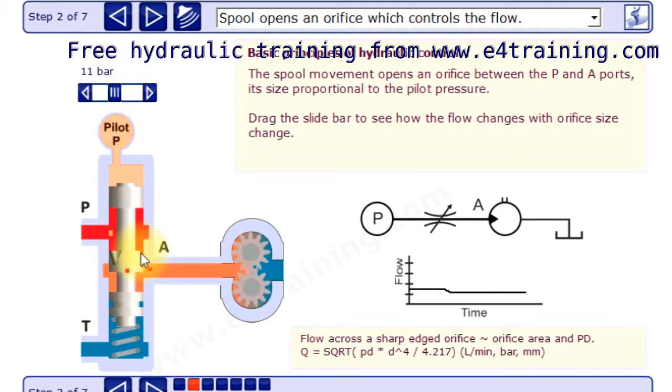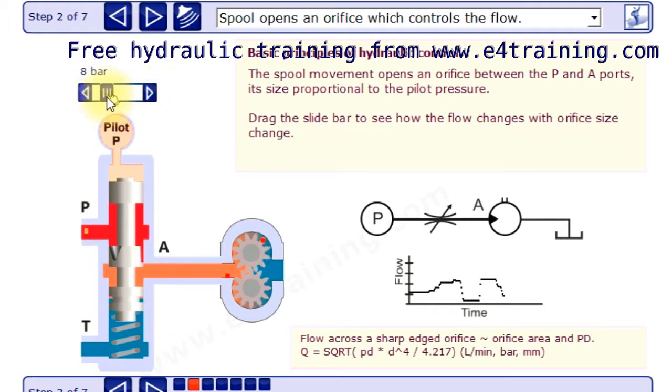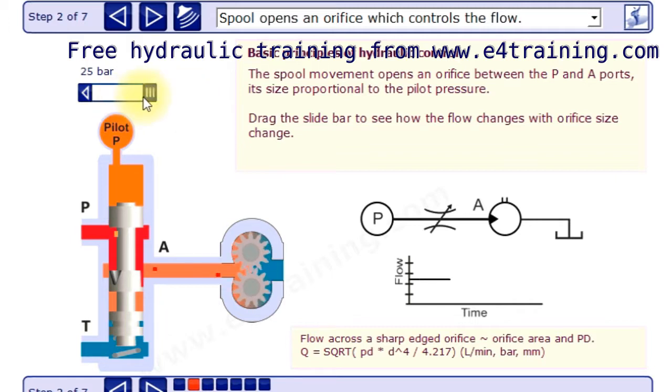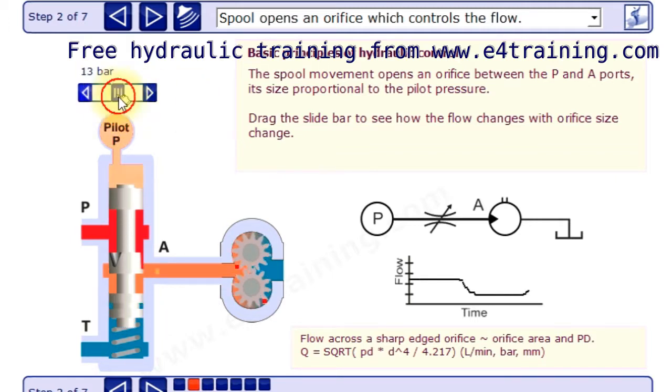And the other thing with the spools as well, you get a lot of flow forces here. You want to avoid getting too high temperatures, which breaks the fluid down. So the design around here is critical. The more expensive, better quality valves would have better shaped notches, or directional valves obviously don't have a notch at all. They just go from one side to the other very quickly. So there is no control in a directional valve. What we're looking at here really is a proportional spool.